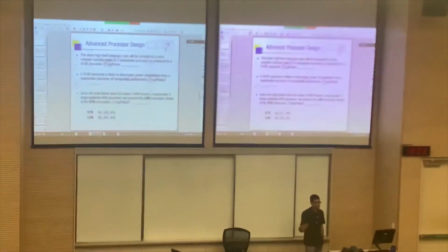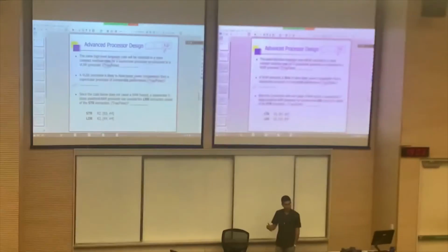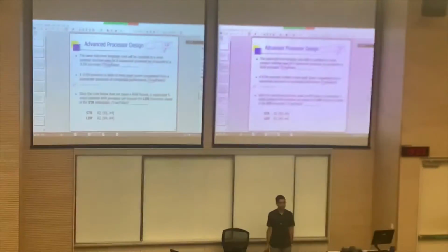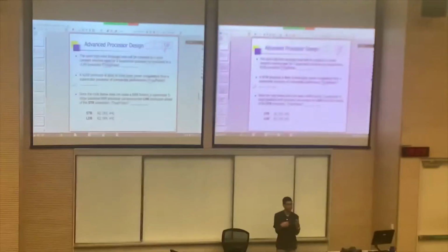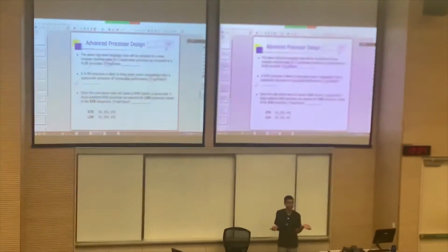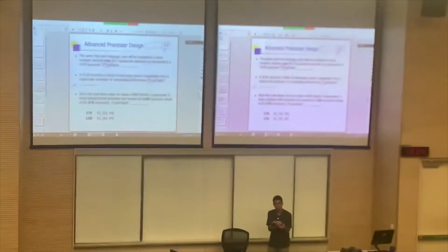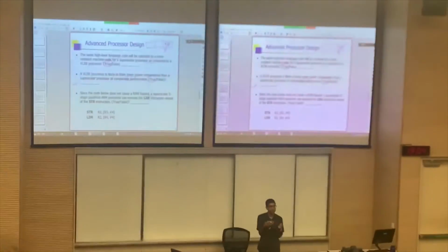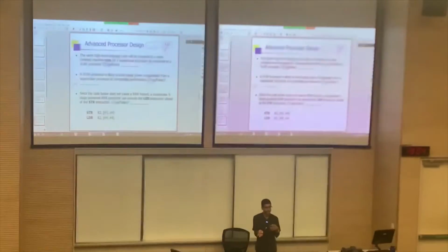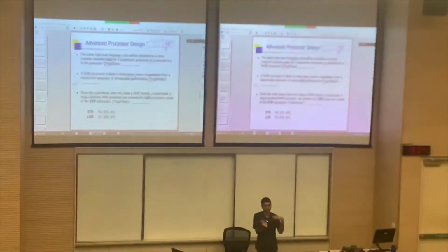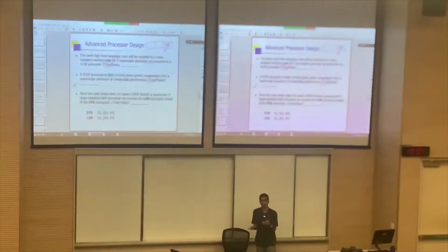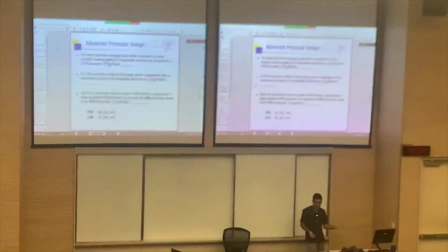And why will it consume less power? Because a lot of stuff is already done at compile time by the compiler, so you don't have to do a lot of runtime analysis, like whether these instructions can go together, etc. So the circuitry that is required to do all these comparisons and dependency checks need not be there. That already reduces your power consumption as well as possibly hardware cost. You also may not require much forwarding, etc., because the compiler will ensure that the instructions are sufficiently spaced, which eliminates the need for forwarding. So all these can reduce the power consumption.